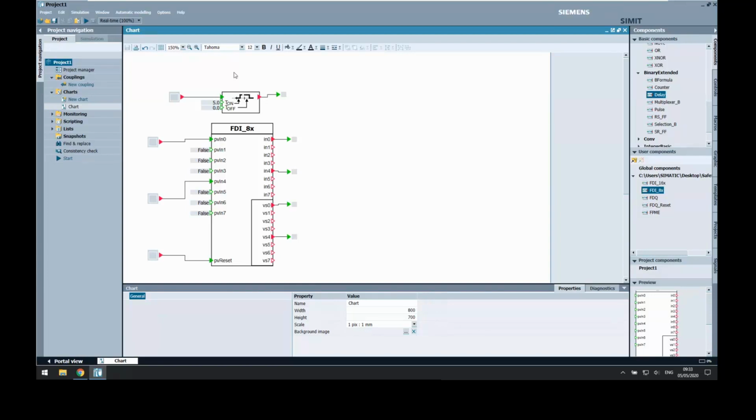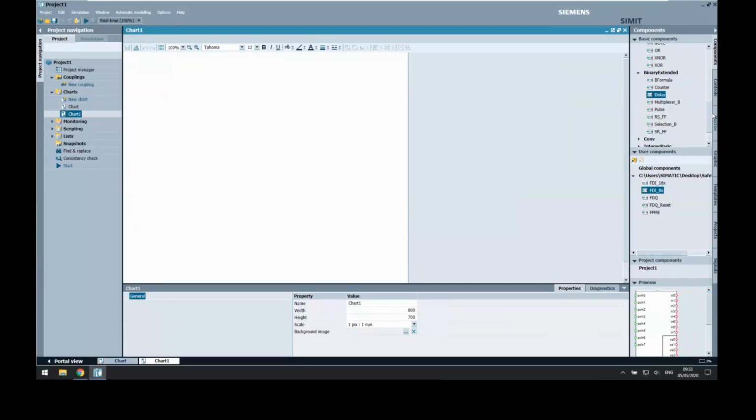Now this chart, because I want it big, let's just leave it like this. Let's create another chart. And yeah, this one's going to be called chart 1. So let's quickly think about how we would maybe create the simulation of steam production. We have these libraries here on the right-hand side that we could use. One of them is FlowNet, and this is specific for water and steam, really, but also does generic gas or liquid. So we can start by adding ourselves a P node, which will be our pressure.